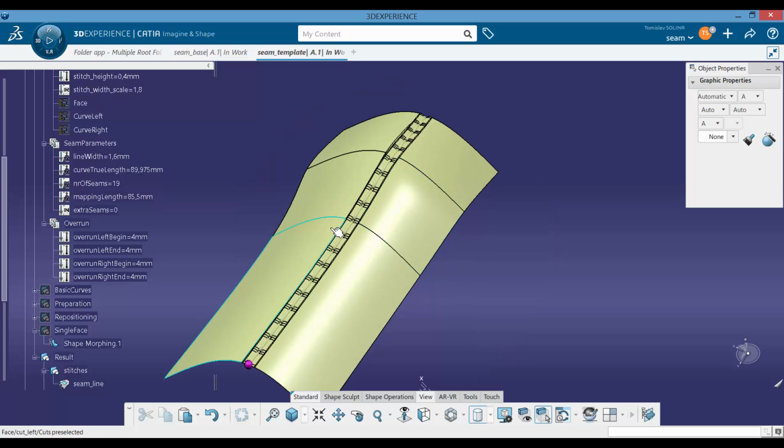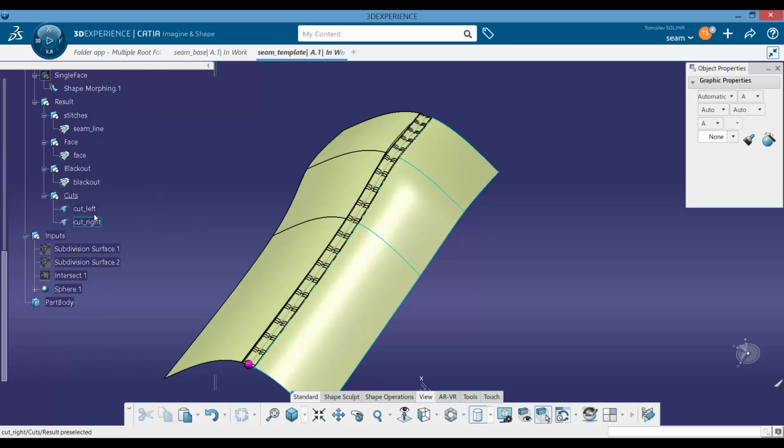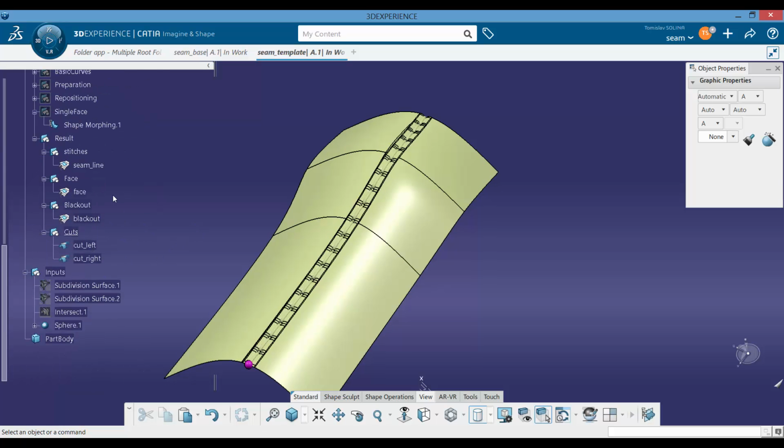Of course, as this is a template it's relatively smart to keep templates as light as possible, so minimal amount of elements so that the data that is saved on the physical disk is actually the minimal, because this will later save you the loading times when instantiating these elements.